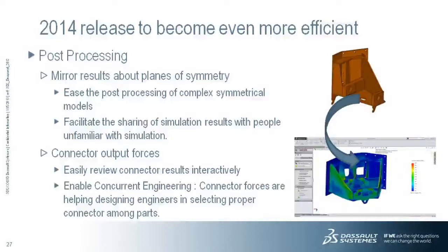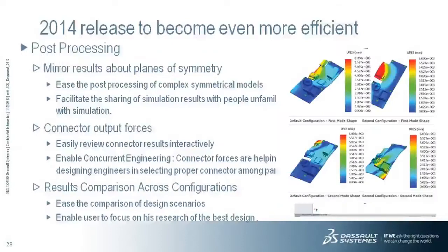We have seen earlier the benefit of using connectors for assembly analysis. In 2014, for spring, spot weld, and link connectors, you can now readily list the output forces after you run a static or a nonlinear analysis. So now with the new release, users get the output forces for all the connectors we can define in SolidWorks Simulation, to dimension them properly inside SolidWorks Simulation.